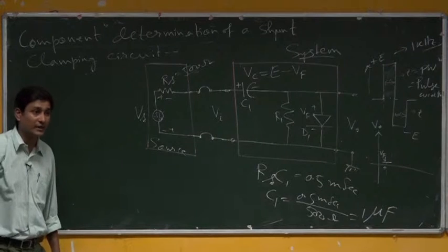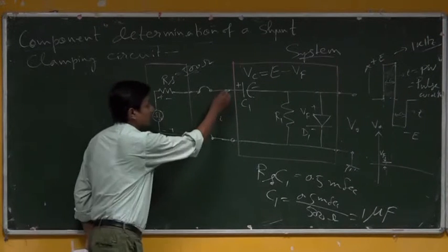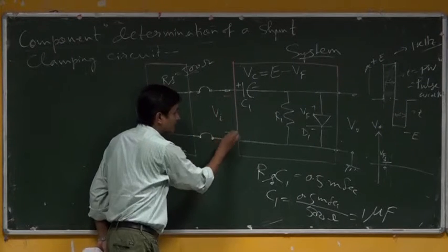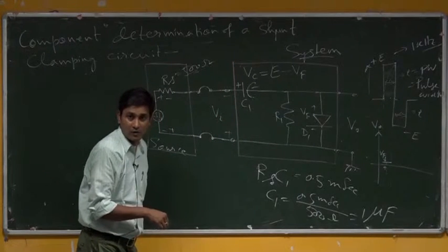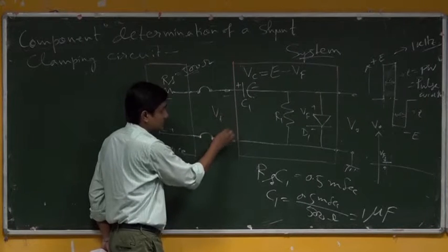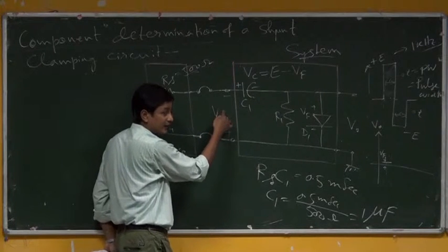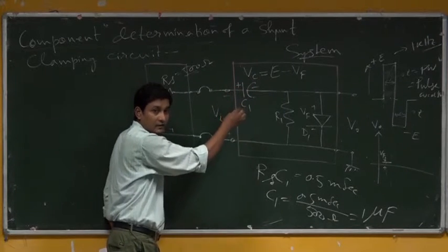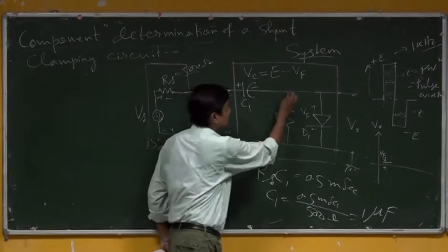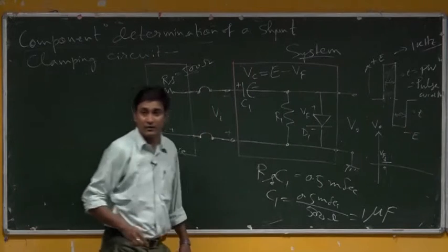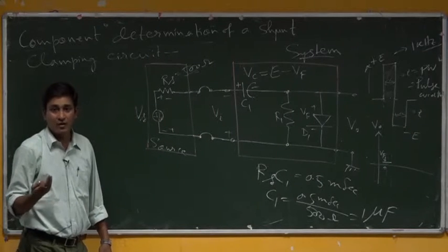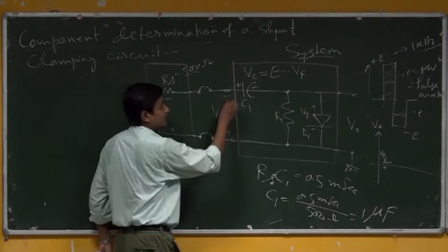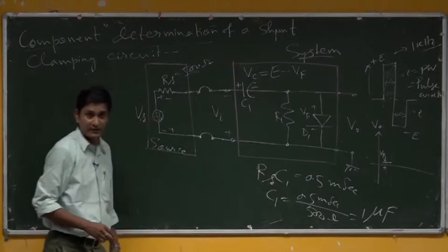If it would be minus E like earlier, because here it will be minus, it will be plus now. But if it is minus E here, and here it is Vc, which is again the negative sign of that, then the total potential across these two terminals, which are actually the terminals of the diode, which is now open, was minus E minus Vc.